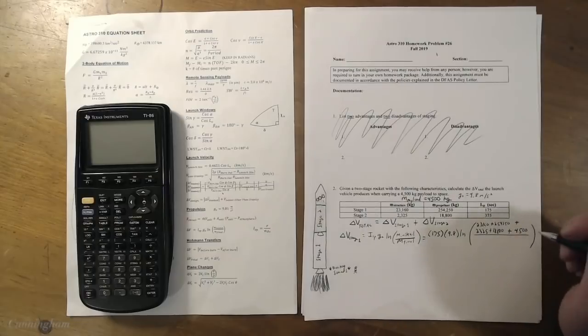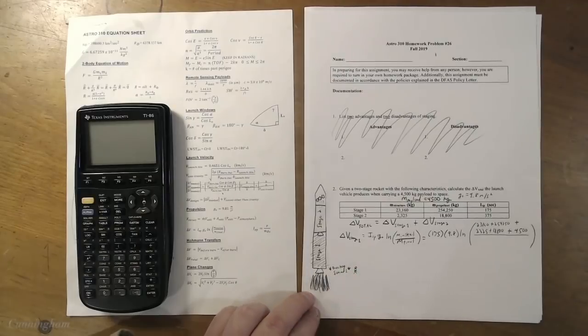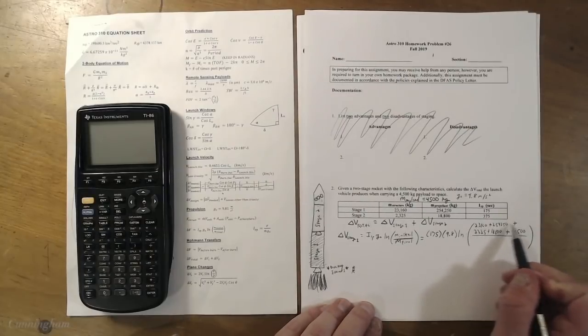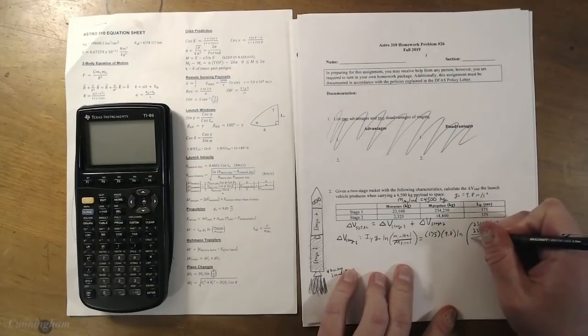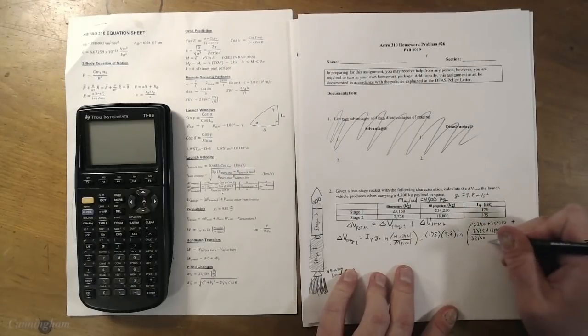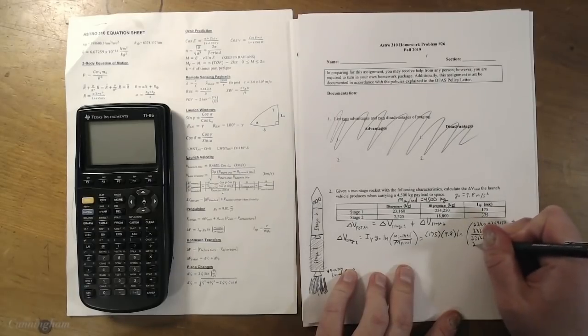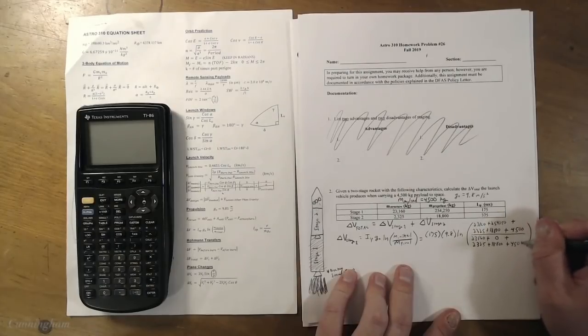Whew. That is mass initial. That's what we start off with, because that's what's sitting on the pad. Now, after we push the big red button and we burn through all this fuel, the mass of stage 1 after it's lost all its fuel is this huge quantity up top minus the propellant, right? So the structure is still attached. The fuel is all gone. Stage 2 is still attached. Stage 2's propellant is still attached. And of course the satellite, you hope, is still attached.